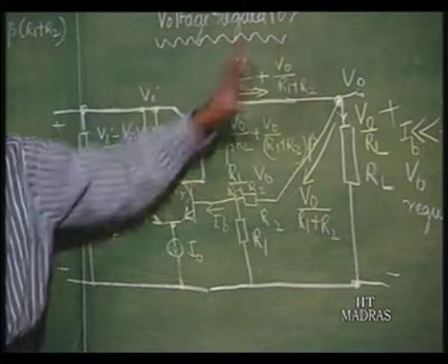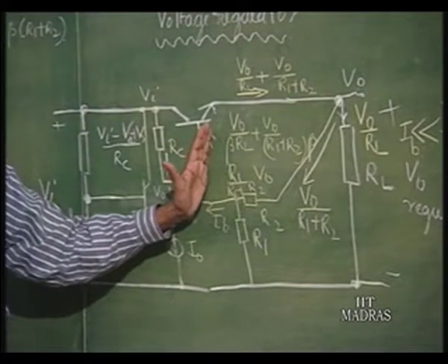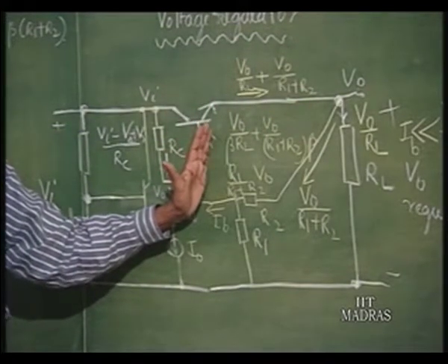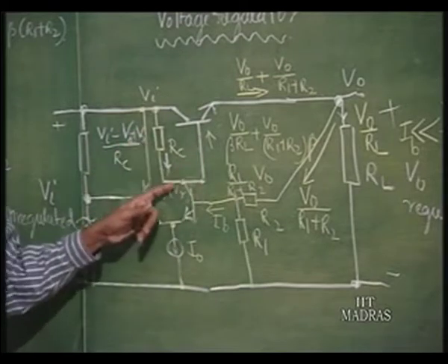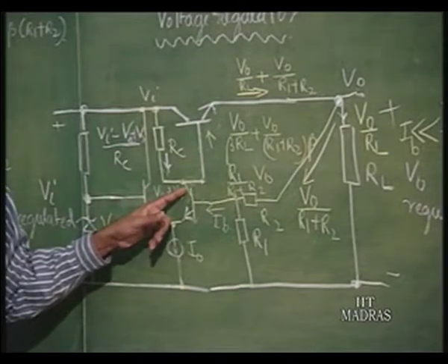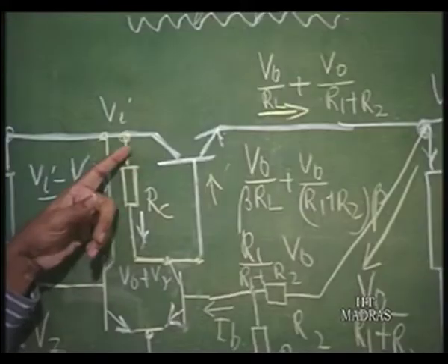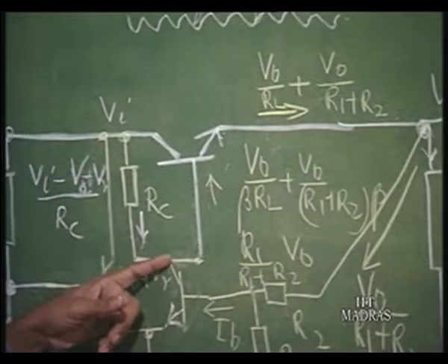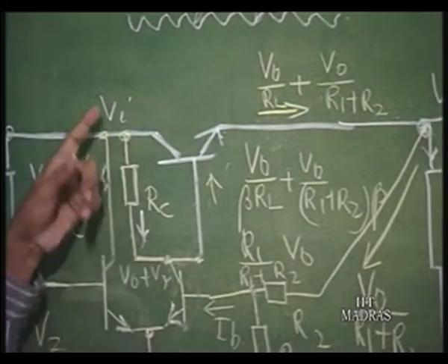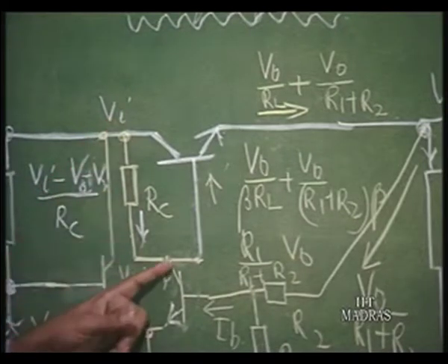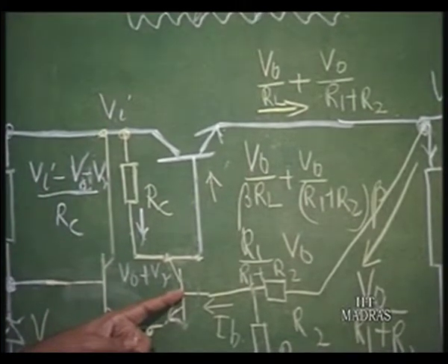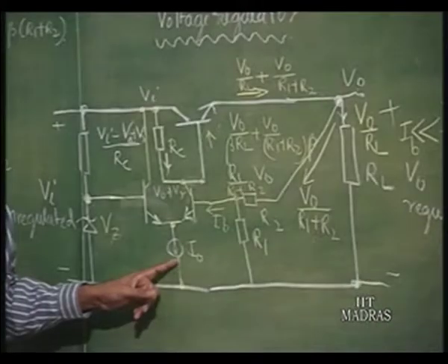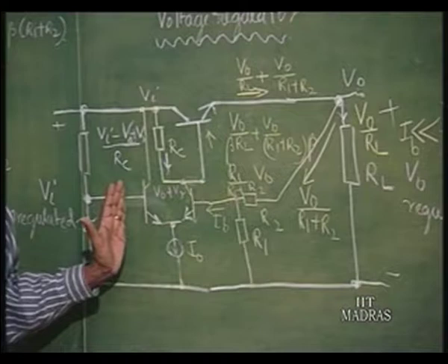So, the base current is a constant requirement of 1 milliampere. So, this current has to be greater than 1 milliampere. Let us say it is 2 milliamperes for a given input voltage. So, this 1 milliampere will go into this. Therefore, I naught has to be greater than 1 milliampere, so that some current is left out for this transistor to remain in the active region.